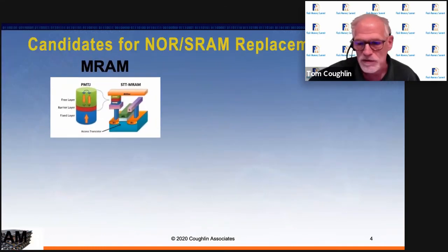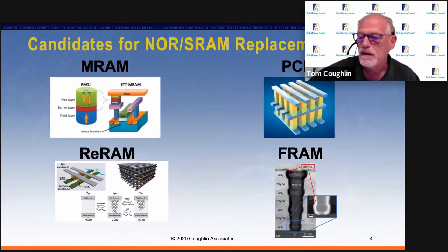And let's meet these persistent memory candidates. They all share the same attributes. They all have a small single element bit cell that promises to scale smaller than current technologies to support small, inexpensive die and 3D stacking. They also promise to be easier to use than flash memory by supporting write in place with no need for a block erase, and they have more symmetrical read-write speeds.